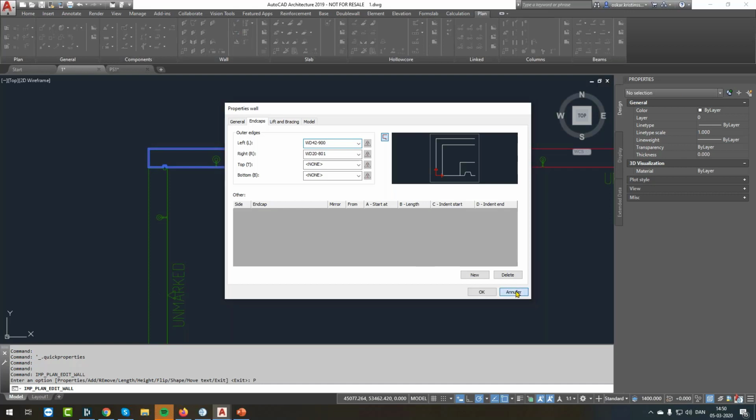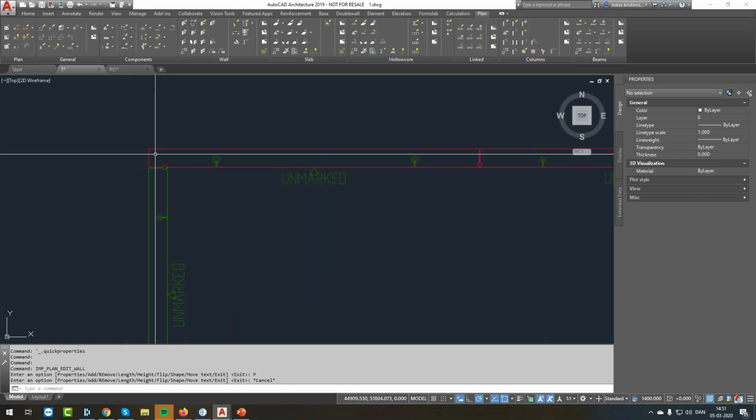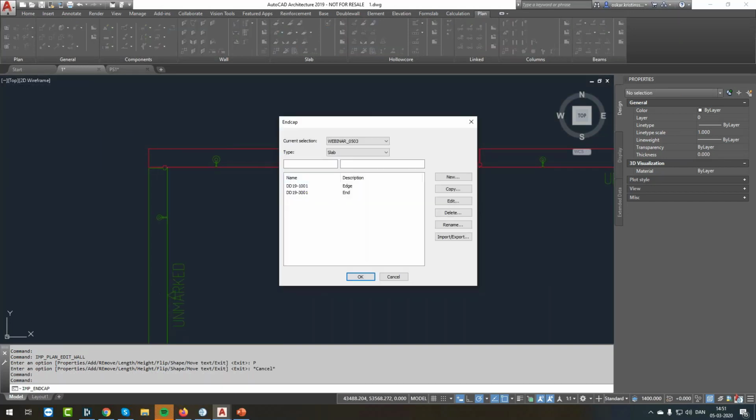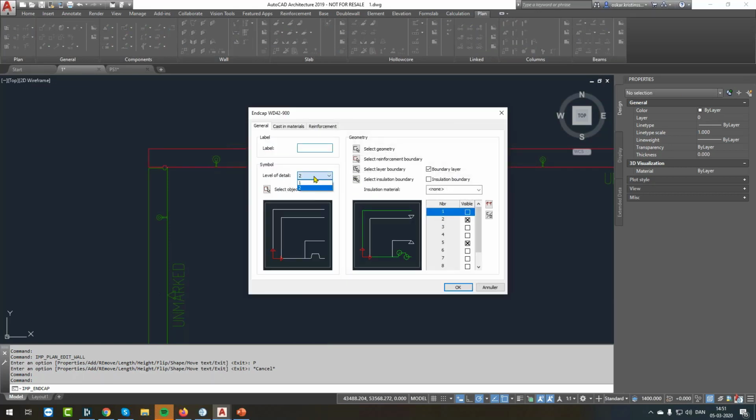The only downside, or what you would call it, of automatically creating this end cap here is that we will have to add level 1 in here, because this here is not generated. So you will have to put in the end cap picture and add the measures you want to be shown on the shop drawing.